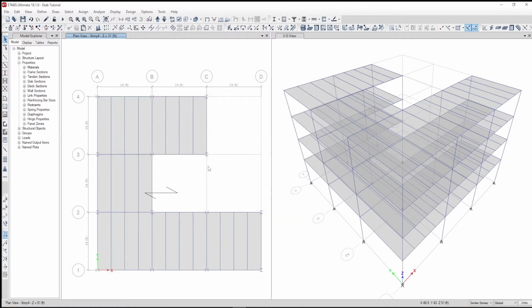Next, we'll add exterior cladding for wind load application. Exterior cladding consists of dummy shell objects that have no mass or stiffness. The areas will be used to apply wind load to the building. Use the Auto Draw Cladding tool to create the walls.